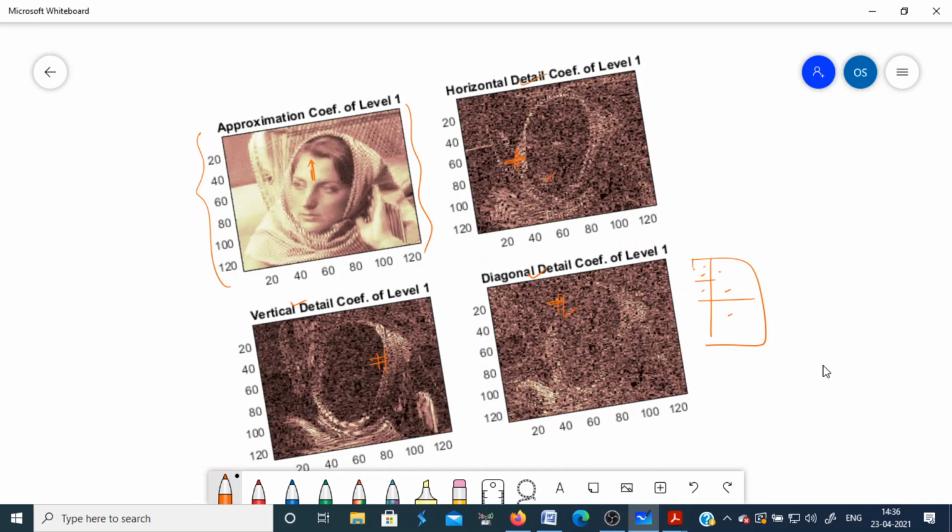So you discard some of these coefficients because you see they contain only the noisy part. Okay. So if you delete these coefficients and you apply inverse DWT, you may remove the noise if this image is noisy. Or you may remove these parts and only store this much, and your image will be compressed. Okay. This is how DWT is used for image compression. And in your JPEG 2000 format, DWT is basically used for image compression. Okay. This is level 1.